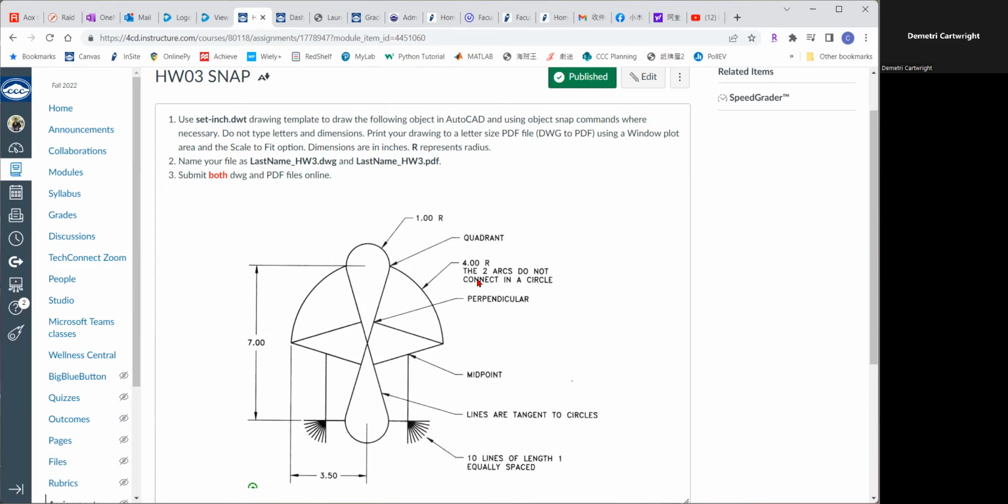The arc has a radius of 4. It's not going to be using the center as the arc center. There are several different ways you can select the arc. Look at the arc selection. The one that you are going to choose is to use the radius and 2 ends. One end is here, one end is here. You can specify 2 ends with the radius, then the computer is going to draw the arc for you.